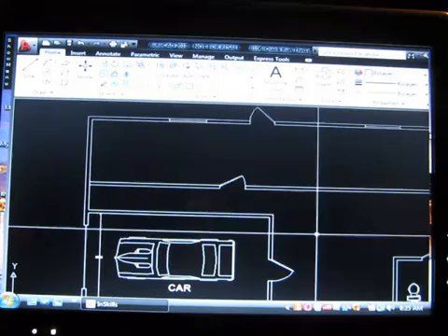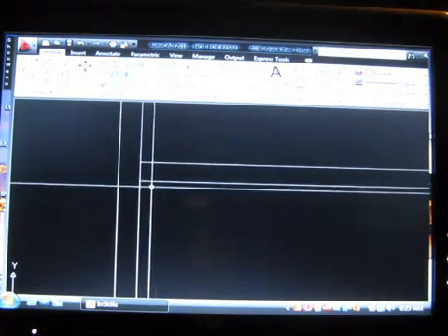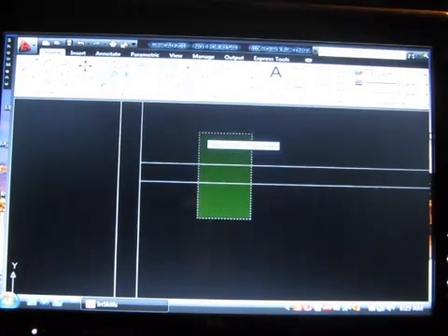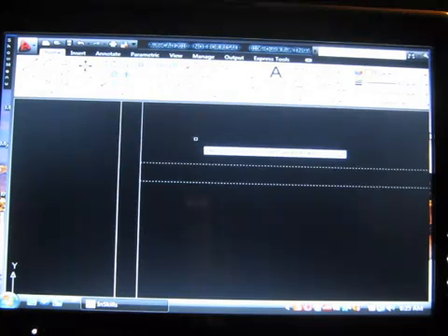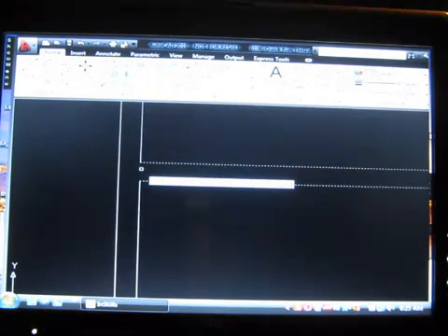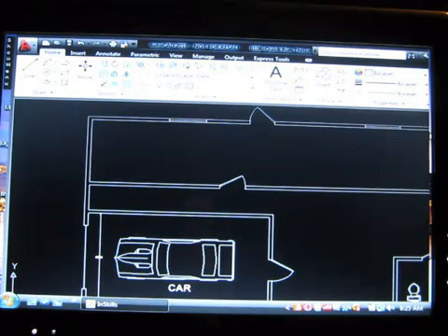And they're gone. Double click the scroll wheel to zoom out. We will zoom back in over here and do the same steps. ER for trim, enter. Select our cutting lines, which is the wall. Enter. Now select the line to cut away, the wall. Enter. Zoom out. These are your basic steps in AutoCAD. This is how you will do almost everything.